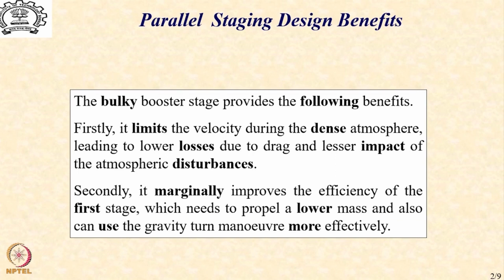Secondly, we note that the efficiency of first stage improves marginally because it needs to propel a lower mass, and more importantly, it can also make use of the gravity turn maneuver more effectively.